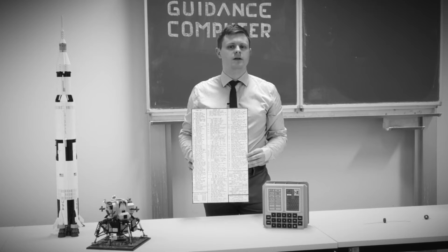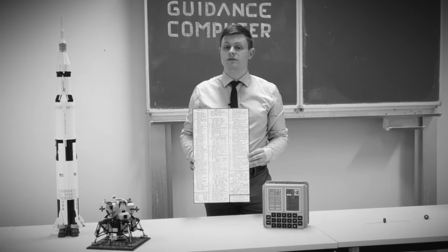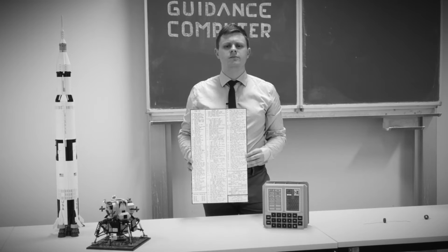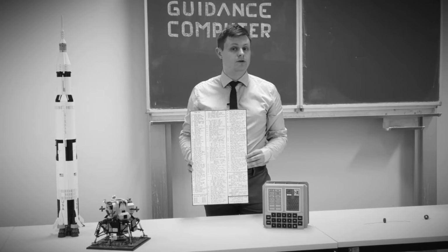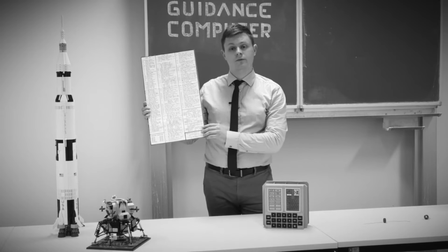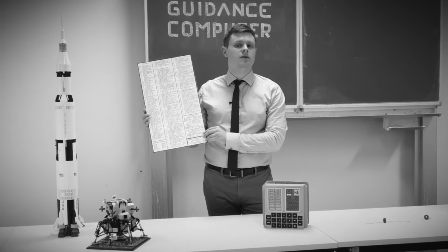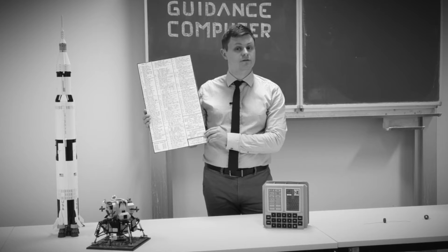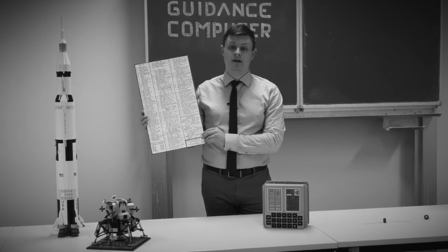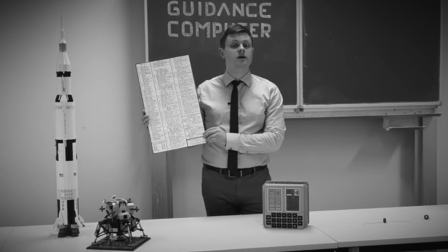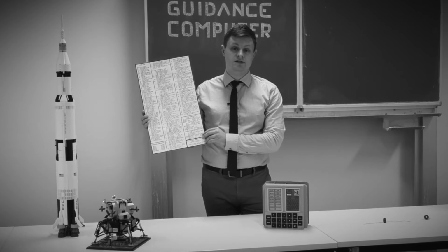Programs, like verbs and nouns, are identified by 2 digits. There are over 40 different programs. A program can be loaded manually by the operator or automatically by an already running program. To load a program manually, verb 37 is used. The noun in this case will be the program identifier. During critical parts of the mission, for example, re-entry, programs are usually only switched automatically by the AGC.